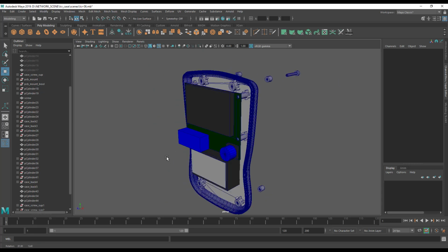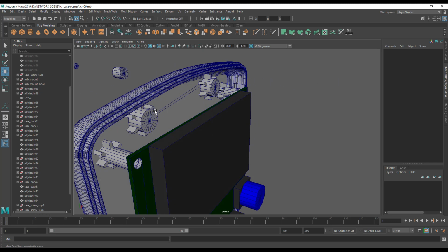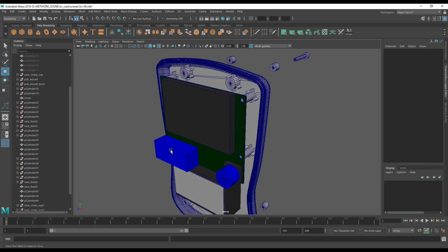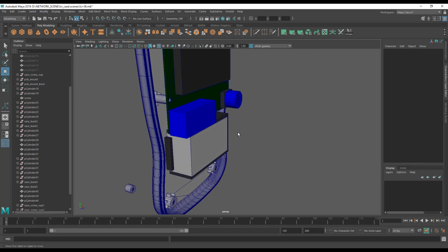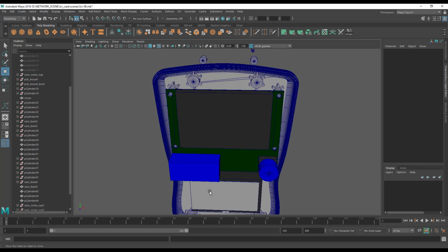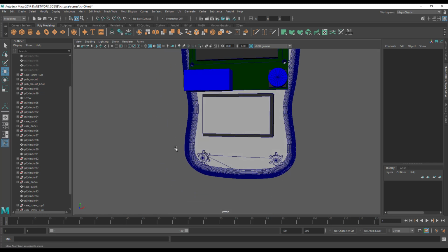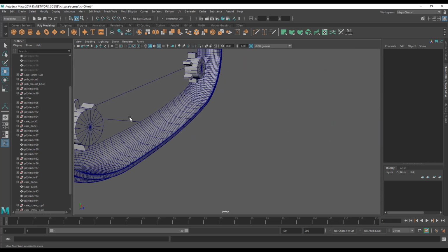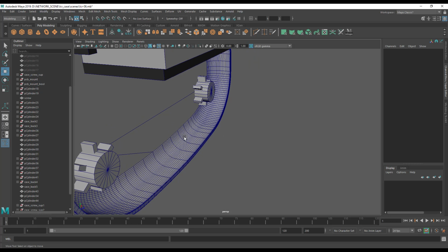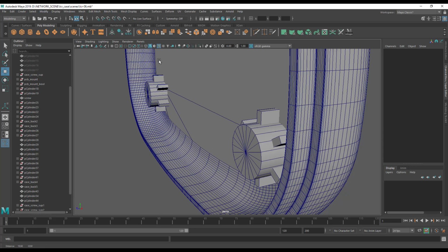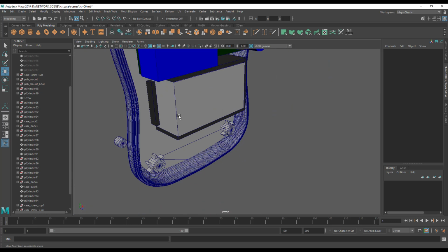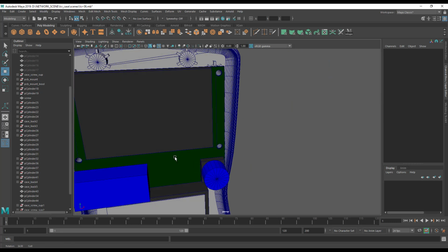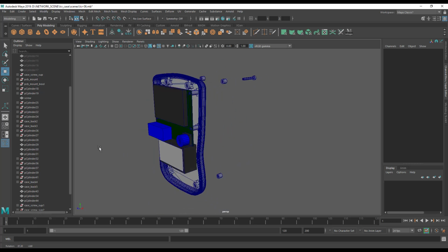the case. In the next part we will finish off by boring some holes, creating some receiving cylinders on the front and back, and then we're going to have to look at cutting all the stuff out of the case. But so far we've done pretty well. We've got a main board secured, we've got the receiving holes ready, we've got everything with little reinforcing nubs around it. You know, maybe these could be a little higher, that's entirely down to you. I tend to think that we have left a fairly generous allotment of plastic, and it depends on what you're printing in. But for me, this should be absolutely fine.